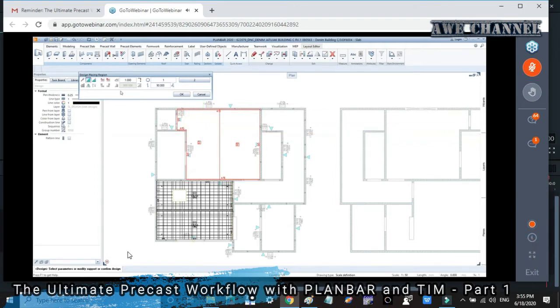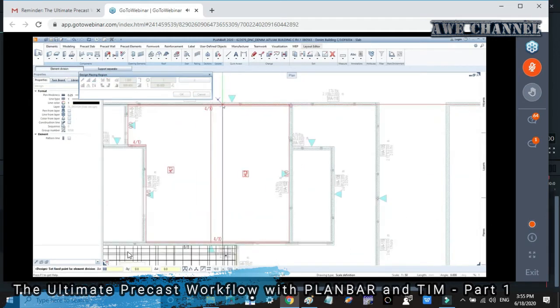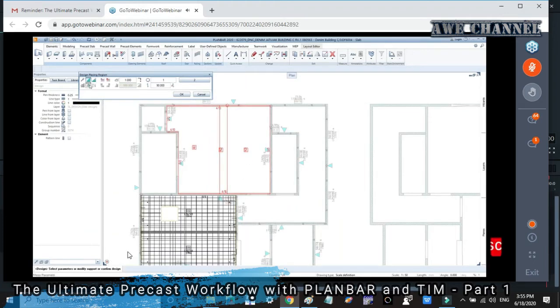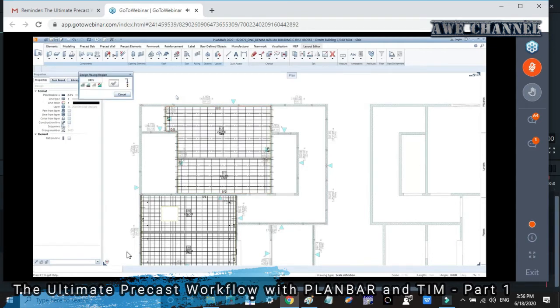If you are not fine with this, you can again change the slab segmentation easily by clicking. And of course, you can change the starting point. But okay, at the moment, the width of houses is over the limitation. I just delete it and create a new slab segmentation here. Okay, it's not fine actually. Okay, or I change the span direction to here. It should be fine. And then I say okay.